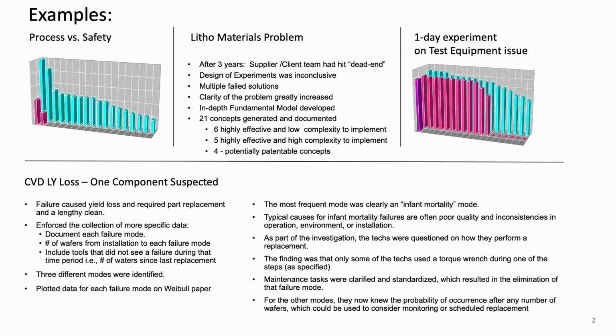Maintenance tasks were clarified and standardized, which resulted in the elimination of that failure mode, because it was essential to use a torque wrench. For the other failure modes, they now knew the probability of occurrence after any number of wafers, which could be used to consider monitoring strategies or scheduled replacement or other maintenance.